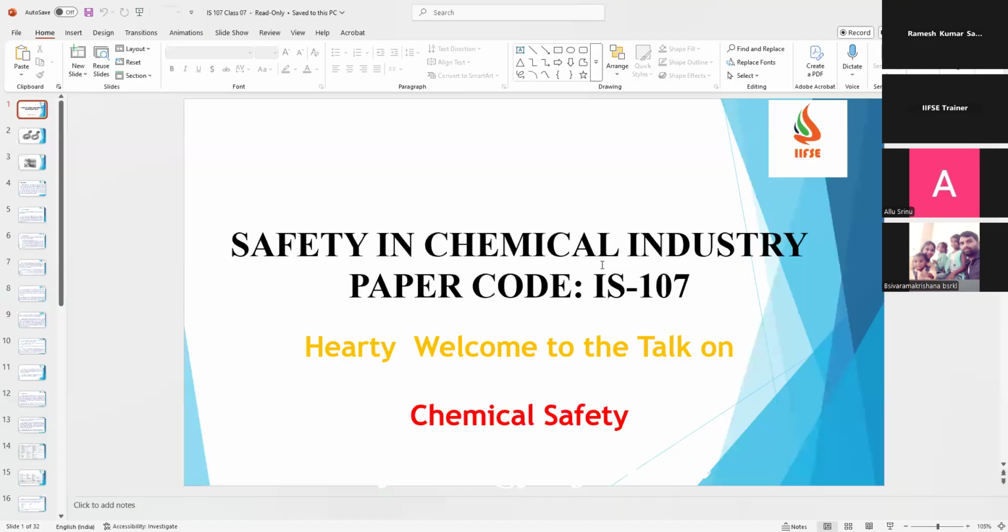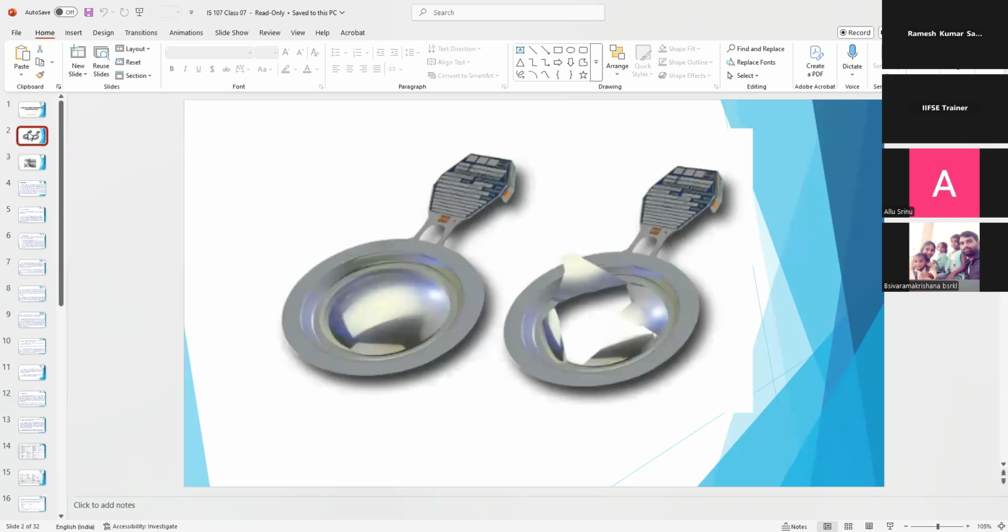So yesterday we were discussing the orifice, or actually the rupture disk. So this is how the rupture disk works. This rupture disk is a new one. When it opens, it looks like this. It just tears off. There is a thin layer of arrangement within this plate. So you will be installing this rupture disk between the flanges so that it can activate or rupture.